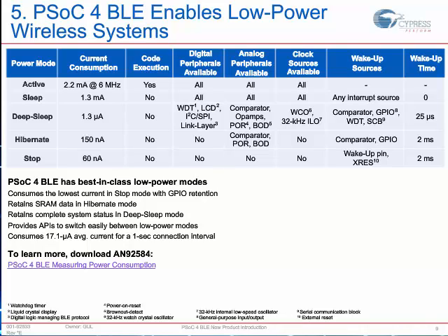But what deep sleep allows you to do is to maintain that connection with your host so that you can, on demand, immediately send data to it using an active mode. What's also interesting and exciting about the deep sleep mode, under the analog peripherals, you'll notice that many of the analog blocks like comparators and op-amps are available and fully functioning in this deep sleep mode, which means your sensor interface, again I'll use the example of my heart rate monitor, can continue to condition my signal at all times, even when my chip is in deep sleep mode.